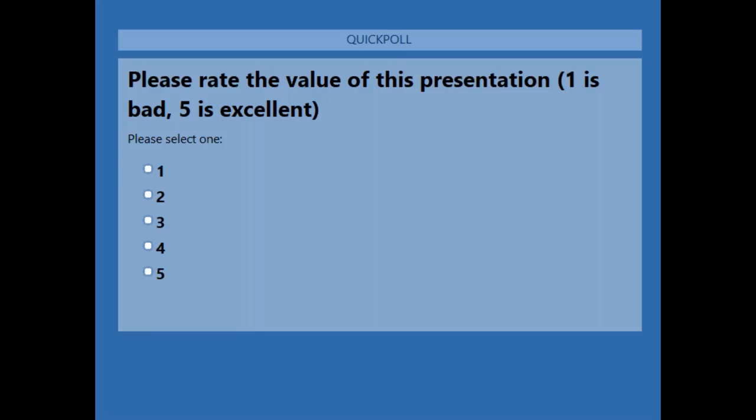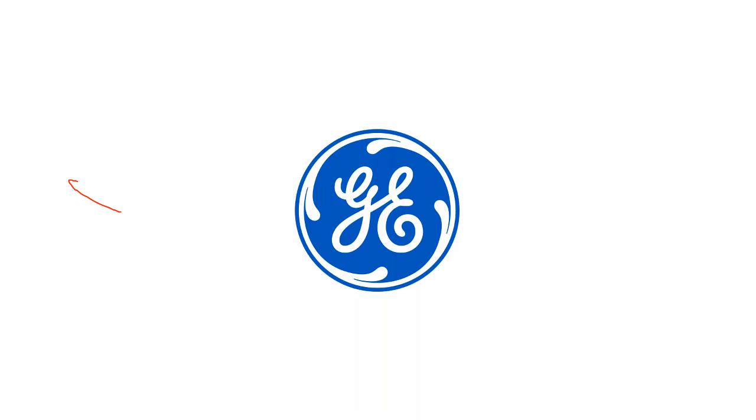So it depends, right? What it depends on is whether it's a stator RTD or a bearing RTD. One of the things that, in my haste to finish on time, I didn't mention was that if we're going to use RTDs, we should use RTD voting. The 869 supports RTD voting.